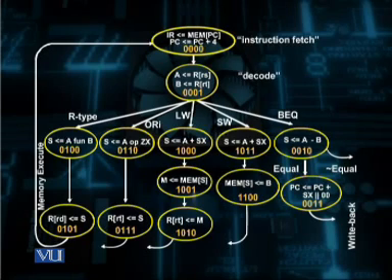This is why you can see that at the next step there can be one of 5 possible next states. If it is an R-type instruction, the next state is one where the required operation is performed on the data, and the result is made available in the temporary register S. So for the register type operations, the next step is the execute operation.